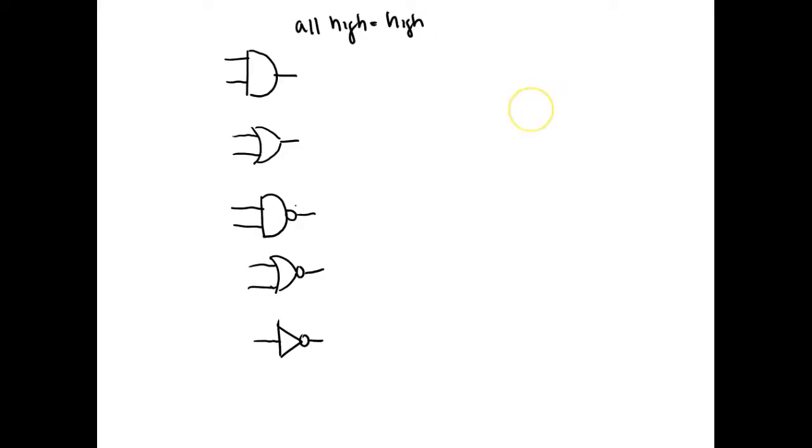On negative logic, your inputs will always be low active, right? So I'll change everything around. Over here I said all. Over here I'm going to say any. Over here I said high. I'm going to say low. Okay, then I'm going to put equal to what? Low. Which would be any, right? Low equals low. What's the difference between those gates? Nothing. They're the same thing. It's a two-input AND gate. It's just how you draw it and how you interpret it in a schematic, right?